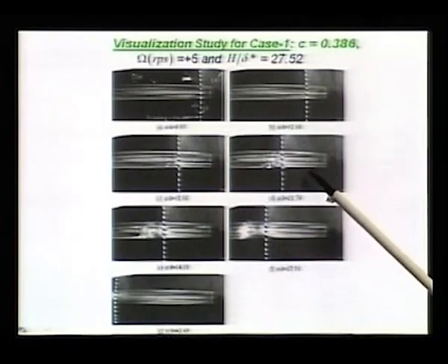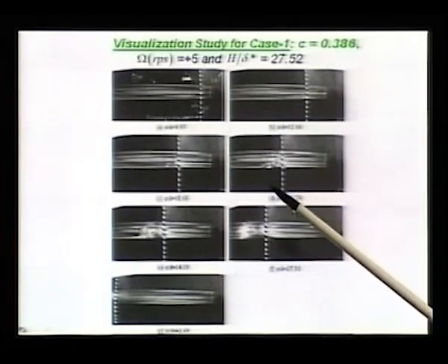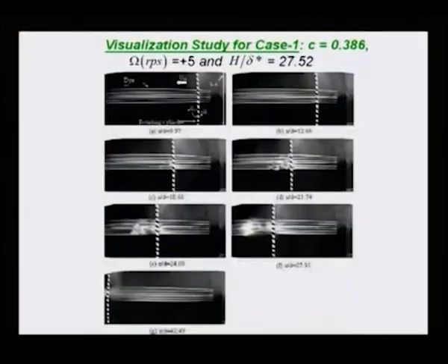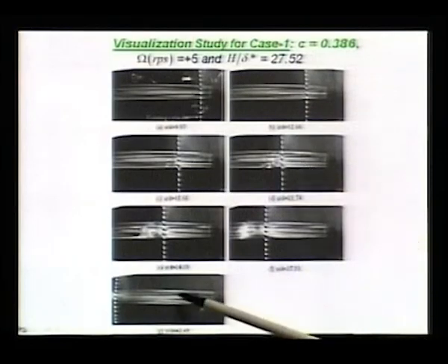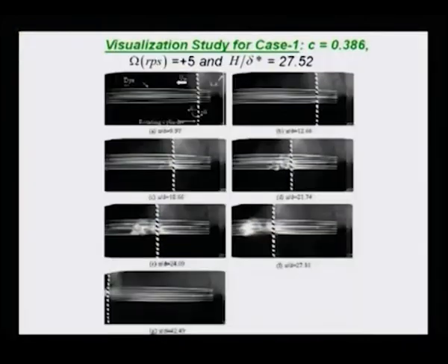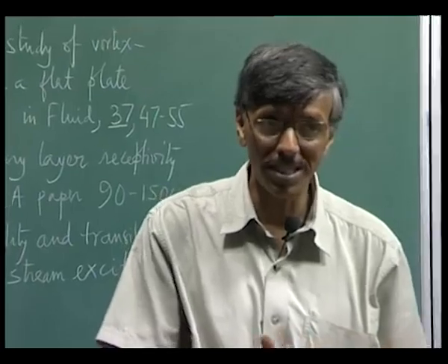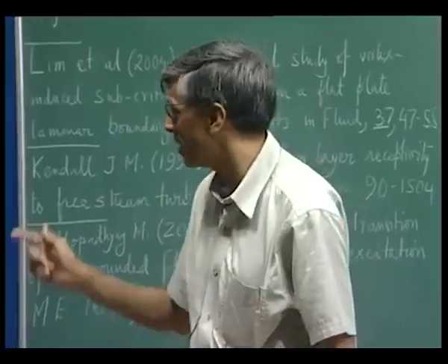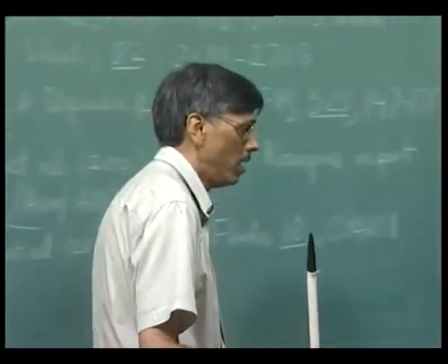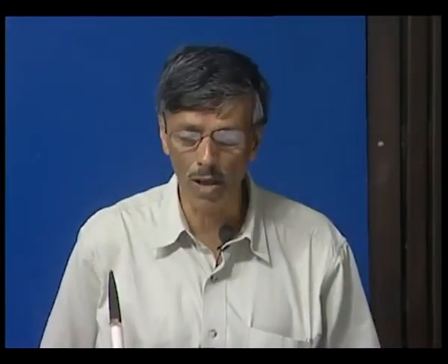And you can also see a very interesting thing: ahead of the cylinder the dye streak meanders, but behind it, it stabilizes and becomes smooth and nice again, and when the vortex is completely removed, you get back your undisturbed flow. It is not only undisturbed flow, but because of the favorable pressure gradient it actually stabilizes the flow, and that is precisely the expression that we noted from that pressure gradient versus x plot.